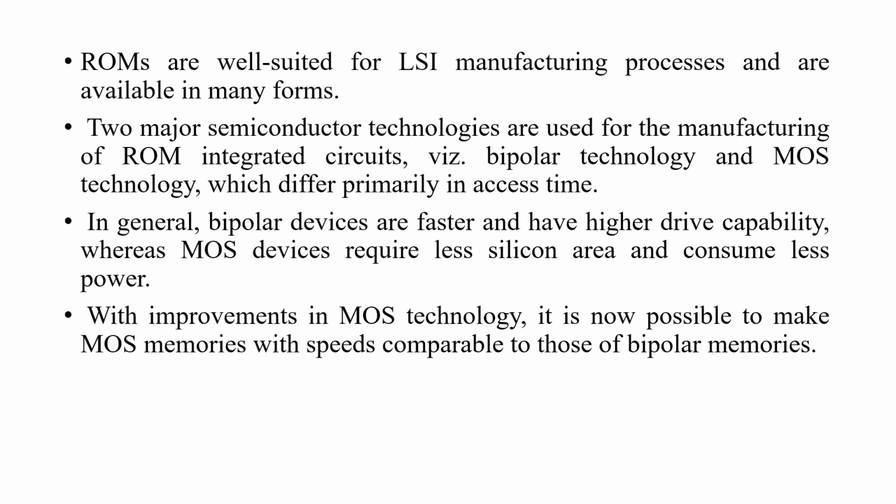In general, bipolar devices are faster and have higher drive capability. For bipolar devices, output current is very high, so these are used to drive more number of devices, so they have higher drive capability. Whereas MOS devices require less silicon area and consume less power.